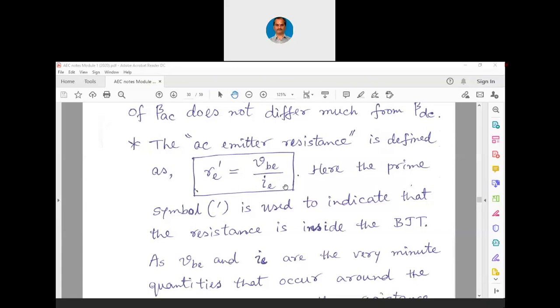If that curve which I showed you earlier were a straight line, we could say that it is a static resistance, where the resistance is common throughout. But it is not the case because the curve is non-linear. When the response is non-linear, resistance keeps changing point to point. Around the Q point, we can consider it a very small linear region.